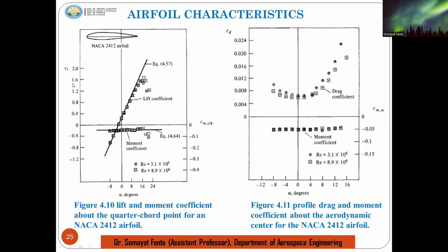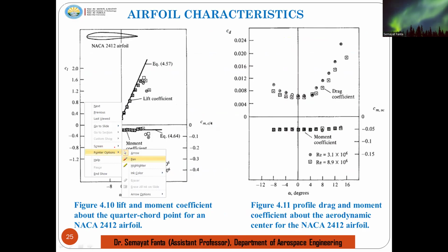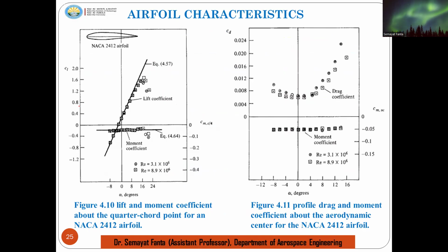So where is the CL value 0.65? It is 0.8 is here, somewhere around. 0.6, 0.8, 0.4, so that 0.6 is here, somewhere at the middle. So tracing it here, straight towards to here, and bring it down like this in straight, then what we can get is the alpha value.